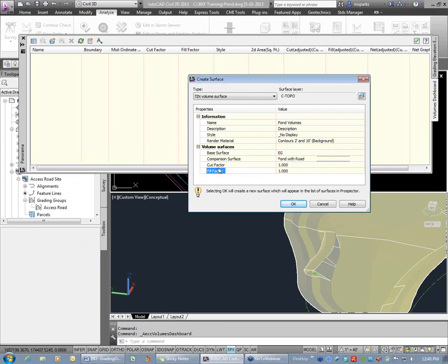If you would like, you can account for cut and fill factors. These are the shrinkage and expansion factors of the geotechnical engineering report if you have one. For example, if the dirt comes out of the ground and gets bigger, what's that percentage? If it's 15% expansion, you could put in the 1.15. I typically recommend leaving them as the raw numbers and dealing with that later.